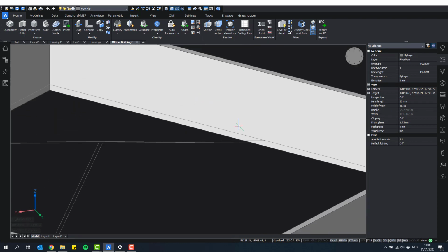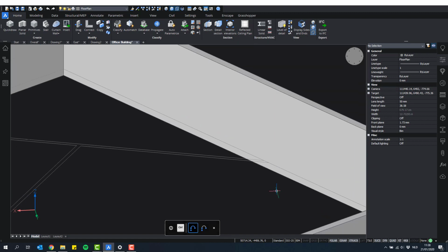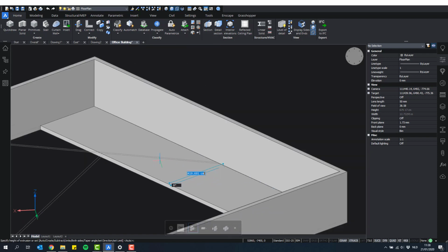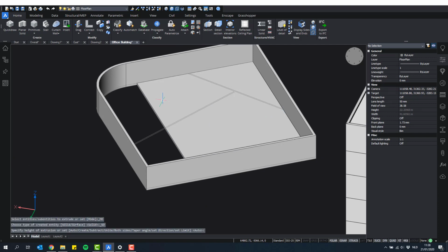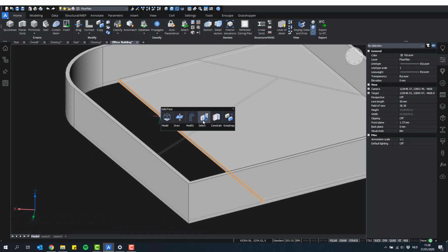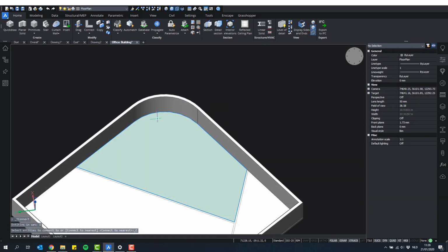The reason I did this is because now you see under this line here at the bottom edge of my wall, now there's a boundary because this line makes the boundary between the bottom edge of the wall and this line. So I can use this boundary again to create new geometry. For instance, I can create a new floor slab by using solid extrude. I will extrude it to somewhere, let's say over here. Now I can use, again, the connect with nearest tool like before to create the floor slab. Now it nicely fits around this round edge here as well.